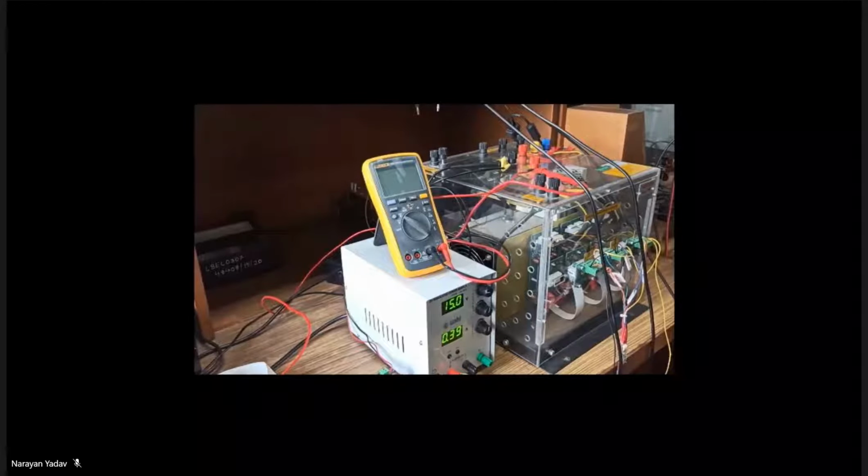In this experiment, we will be taking a couple of measurements by setting the DC link voltage and modulation index. Your job is to note down the load magnitude, DC bus voltage and DC bus current, RMS load voltage, fundamental magnitude, load current and THD.